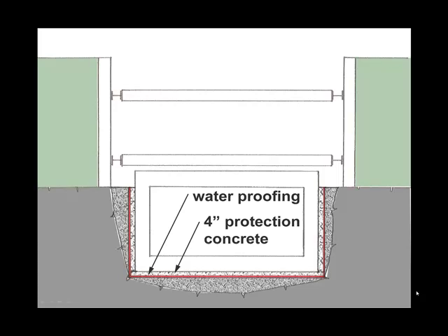The process being used here on this project and on the earlier project showed concrete being placed up against a waterproofing membrane. That membrane has to be perfect because any penetration of that membrane will create a path for the water in your permanent structure.